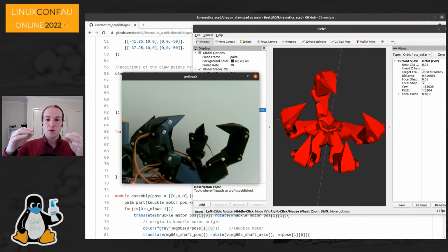You can have a function on the microcontroller that avoids the obstacle in a hardware real-time loop, and then the host system picks up all of those points, generates a map, and builds a motion plan for the robot to follow. That way you've got the hardware real-time safety guarantees of an onboard obstacle avoidance system, with the niceties of a more complex map generation and path planning tool.